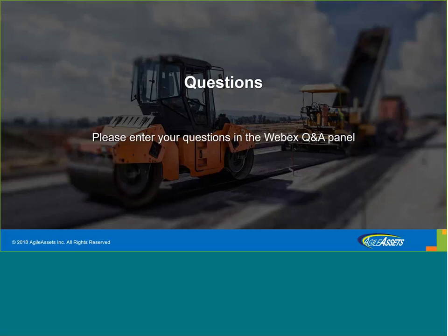We have a clearinghouse for that, the crash modification factor clearinghouse. It has information on different treatments that you can consider for your safety mitigation, and also a list of crash modification factors or crash reduction factors that you can consider when you are coming up with the countermeasures. Generally speaking, if you have the highest crash reduction factor, you consider that for your safety program.